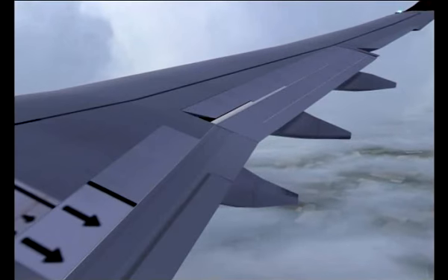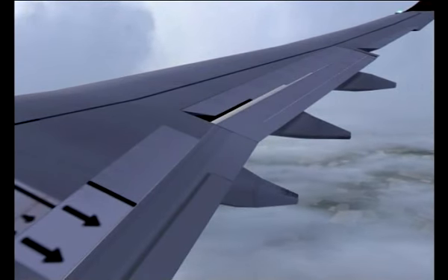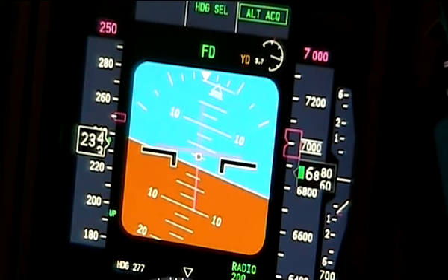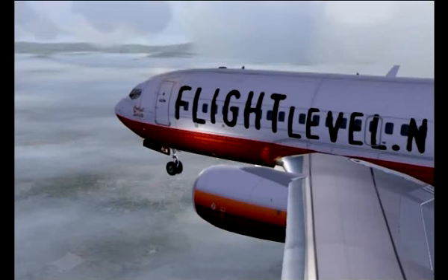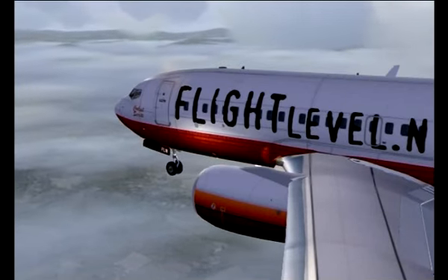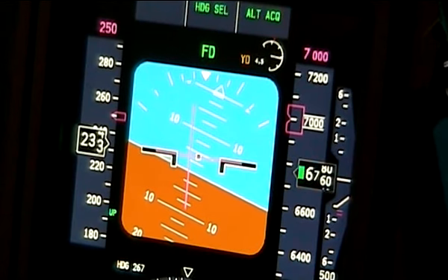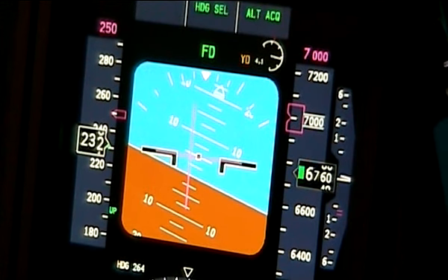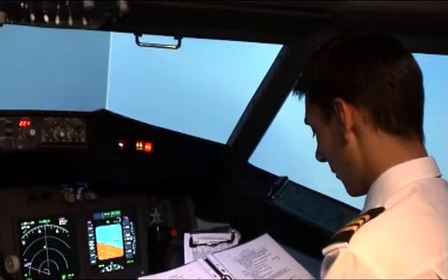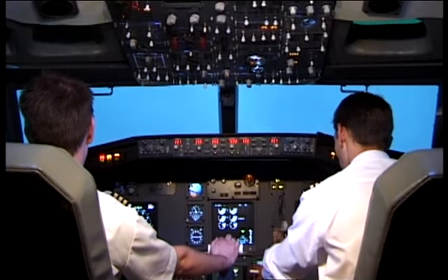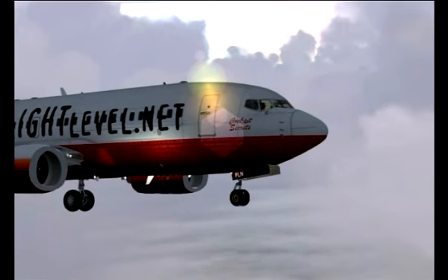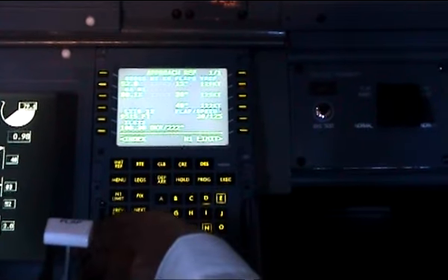Pilots should be fully aware of how the operation of the aircraft's other systems is affected by the loss of hydraulic system B. In this particular case, it's the flaps that require special attention, as they are normally driven by hydraulic system B. With the loss of hydraulic pressure, a backup electric motor should be used. But deploying the flaps with the electric motor takes more time. Plan for flaps 15 landing. Landing must be accomplished with flaps 15, which is also suitable for a go-around.